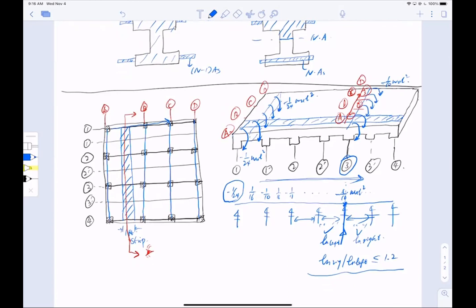No, they're not exactly the same, they're just going to be this direction. So the moment will be uniform across that 3-span? Yes, that's the confusion. It was asking you about along this, it says continuous span, but actually that is the transverse direction. That's not the longitudinal direction of the one-way slab direction.